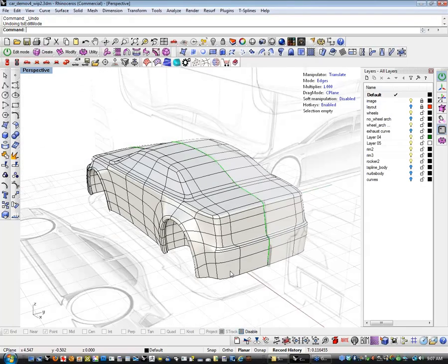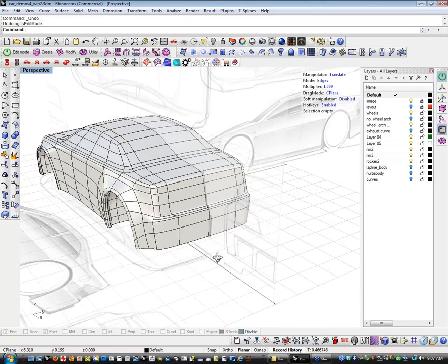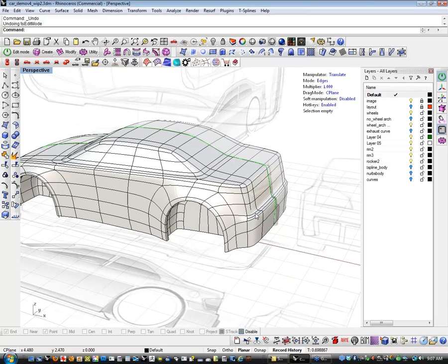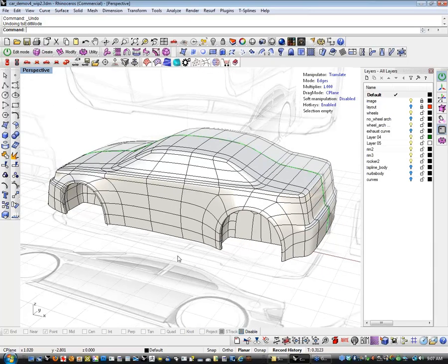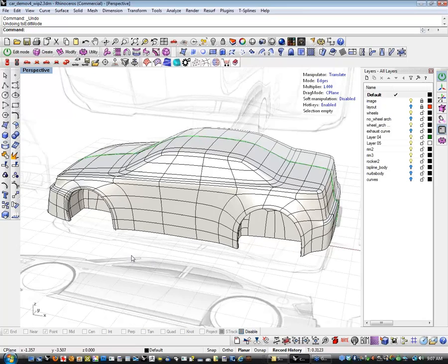We're going to add that big obnoxious rear diffuser thing, and then talk about how to approach some of the other detailing. And then something that I really want to show towards the end is how, once this thing is converted to NURBS, you can precisely trim areas of the car and then actually build new T-Splines pieces off the edges of the NURBS data.